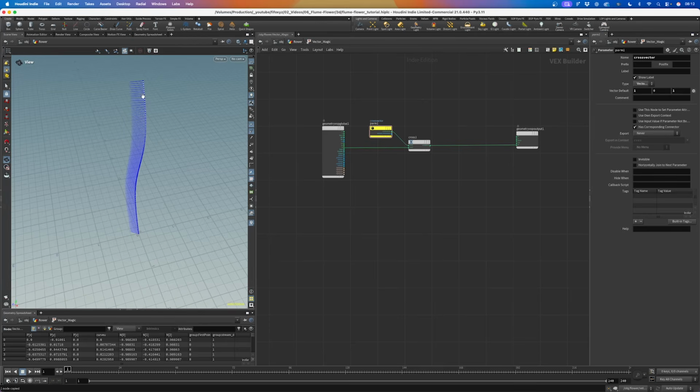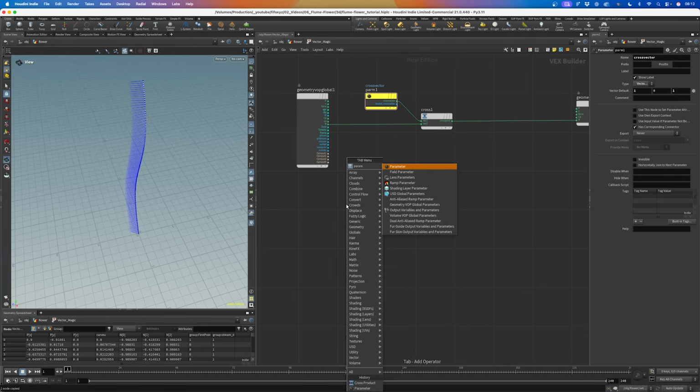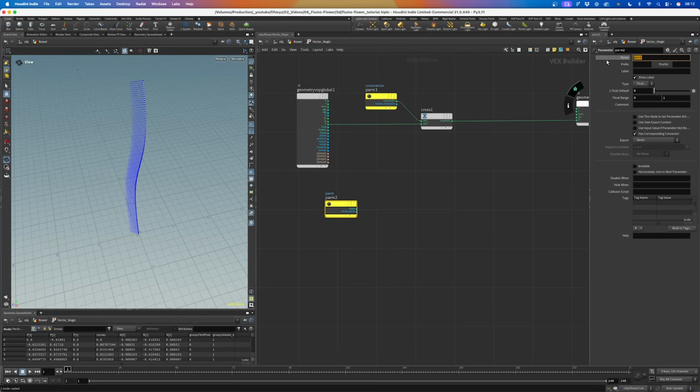And if you look at flowers, as we just learned in the beginning, everything is aligned according to the golden angle. So let's get this thing in here. Let's drop down another parameter, call this golden angle, and let's set this to 137.518 degrees. It's a float attribute. And now we want to rotate each point by this angle.